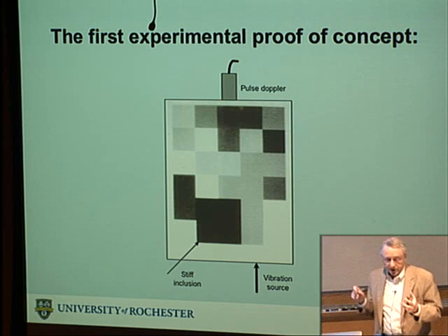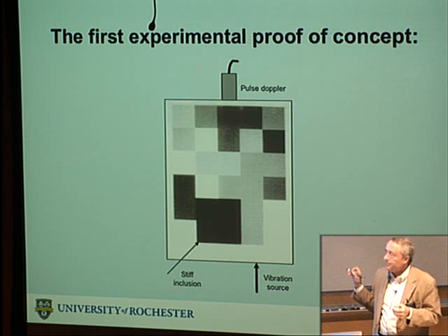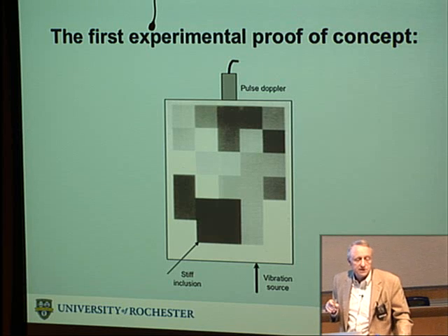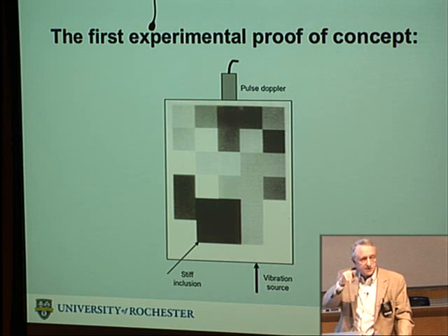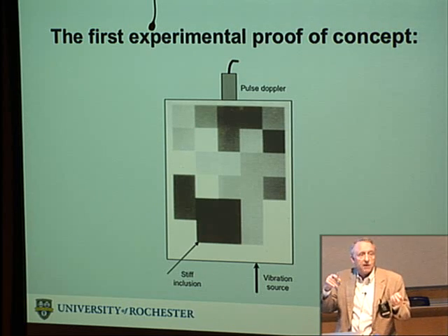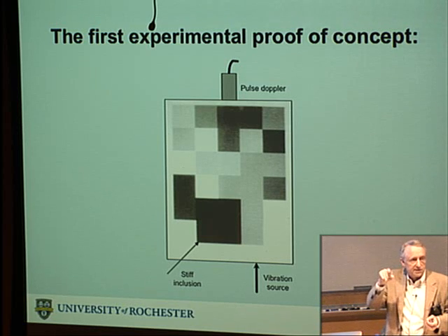And what kind of vibrations are we talking about? Are we shaking people around? Well, with Doppler, pulse Doppler ultrasound at, let's say, 5 megahertz typical frequency, you could pick up 2 microns sinusoidal steady-state vibration at 100 hertz. So a red blood cell is 8 microns. Okay? We can pick up 2 microns of sinusoidal steady-state vibration.